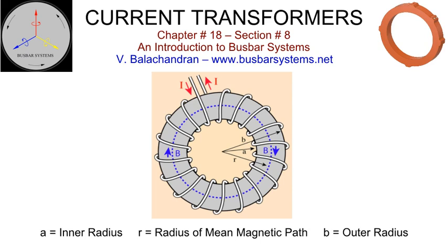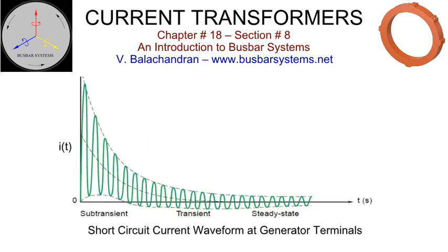Current transformers can be assigned a standard secondary current rating of 1 ampere or 3 amperes or 5 amperes. The selection will depend upon the system parameters, type of device connected to the secondary, lead resistance, and constraints expressed by equipment manufacturers to accommodate them on the generator terminal bushings or inside the tank on transformer terminal bushings. Current transformers are static, passive devices and therefore, if they are well specified, designed, manufactured, and installed, will require no maintenance for the life of the component.